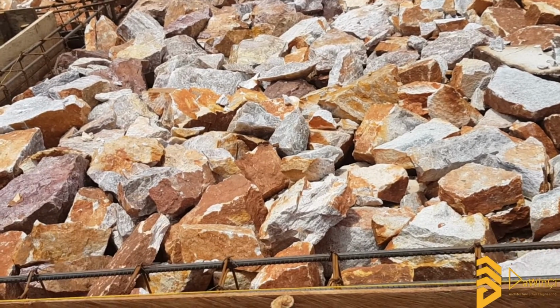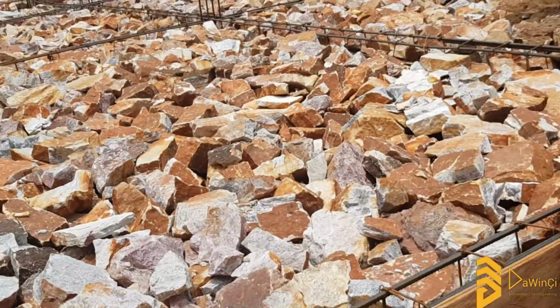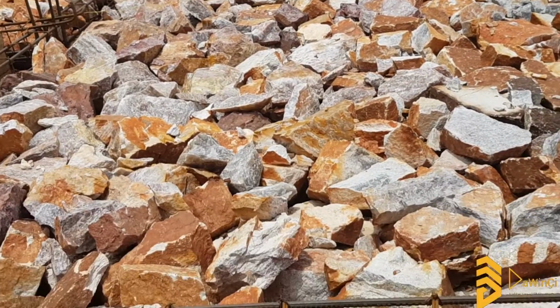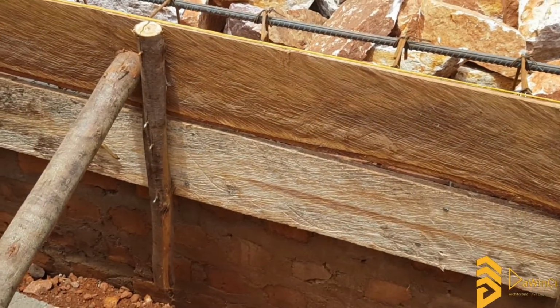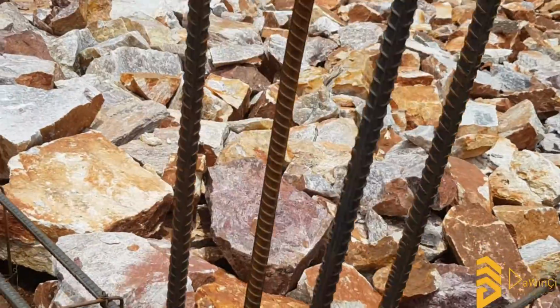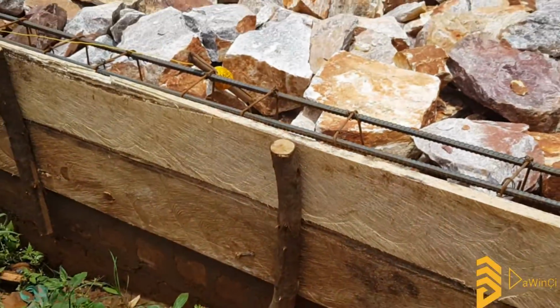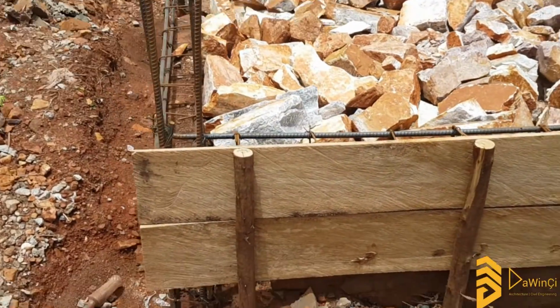Now hardcore, it is not in every scenario that you need hardcore. Like I said previously, when you understand these things, sometimes you can learn to avoid certain things. If you literally have very stable soils and you've not done a lot of backfilling, you might not need hardcore, and usually when you have smaller spaces. So hardcore has basically two functions.